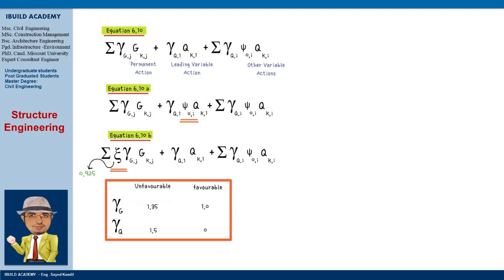An unfavorable action is one that helps, for example, the foundation to fail, when the vertical load is downwards. There may be some situations where an action is favorable, such as an upwards load, which helps to stop the foundation failing. A permanent action has a partial factor of 1, since to make the design value of the action higher would not be conservative. A favorable variable action has a partial factor of 0, because it may not always be there.